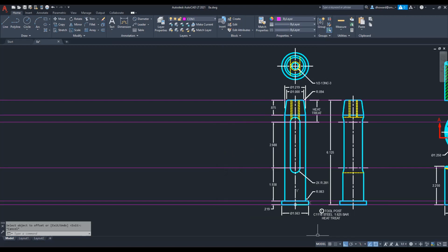Okay, how about the vertical lines? Best to start off with a center line when the object is round. So we'll put one right there, and I'll just put one, yep, kind of randomly right there. And then we'll offset the same amount in both directions, or you can just go to one side and then mirror to the other. Your call.